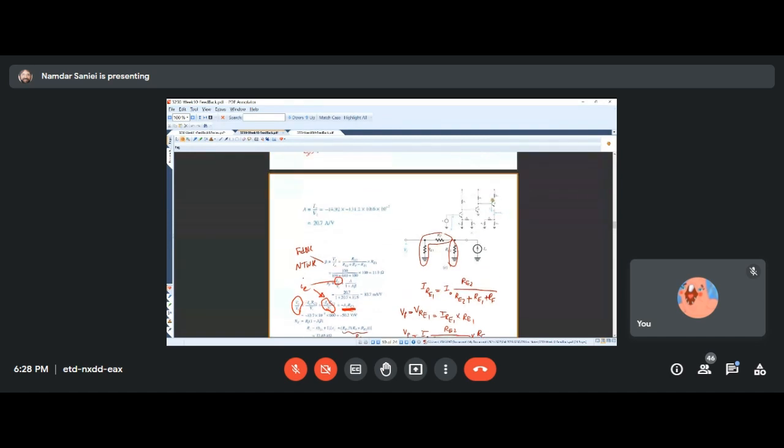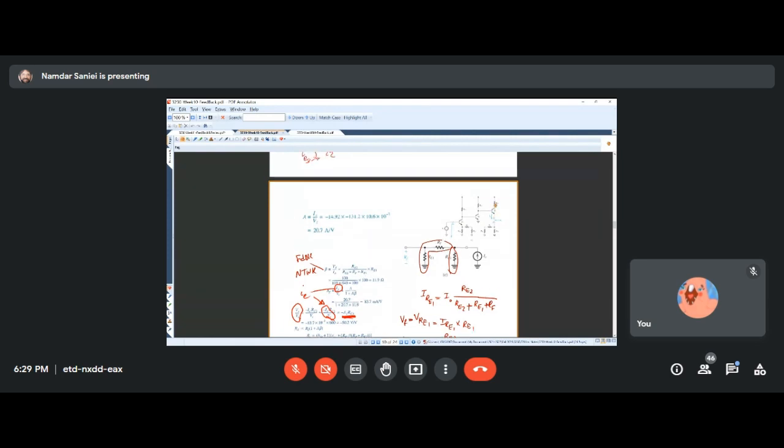Now, if we wanted to go to the voltage gain of the circuit, because the output voltage was simply related to the output current of the loop, and in fact it was almost equal to that output current, we would have to multiply this RC3 by that current to get the output voltage. So in AC, that's how the output voltage is made.